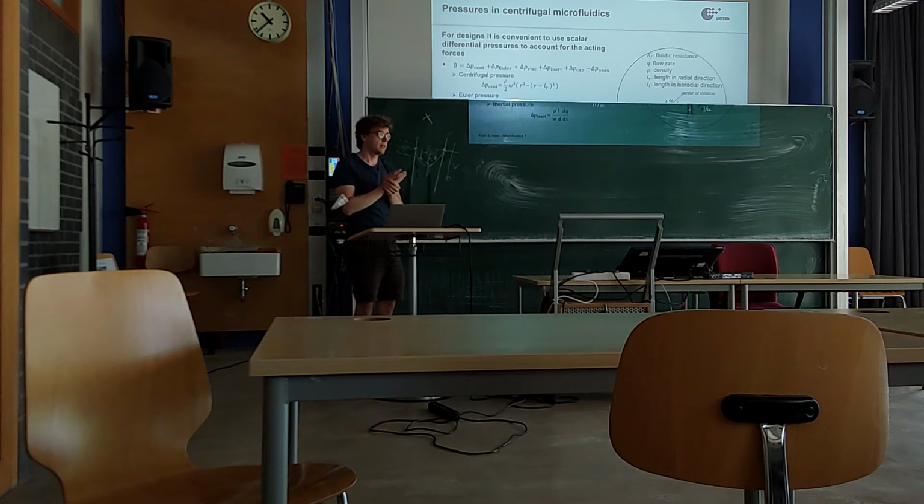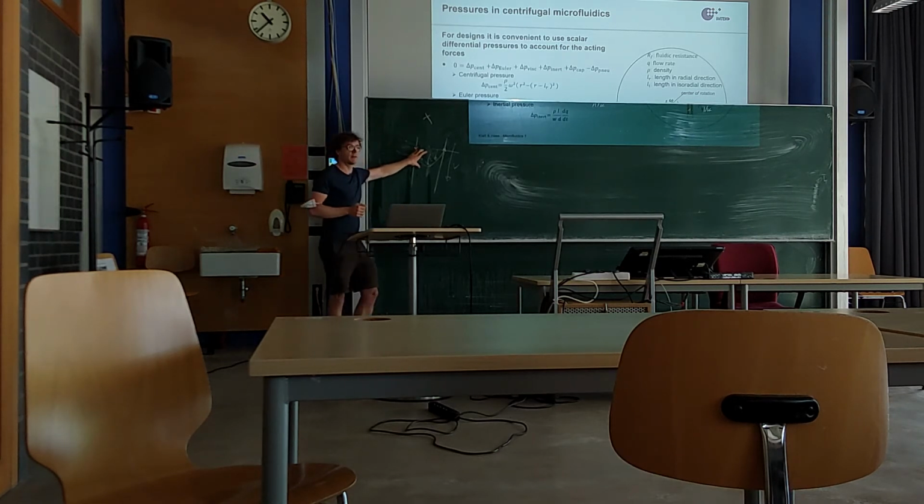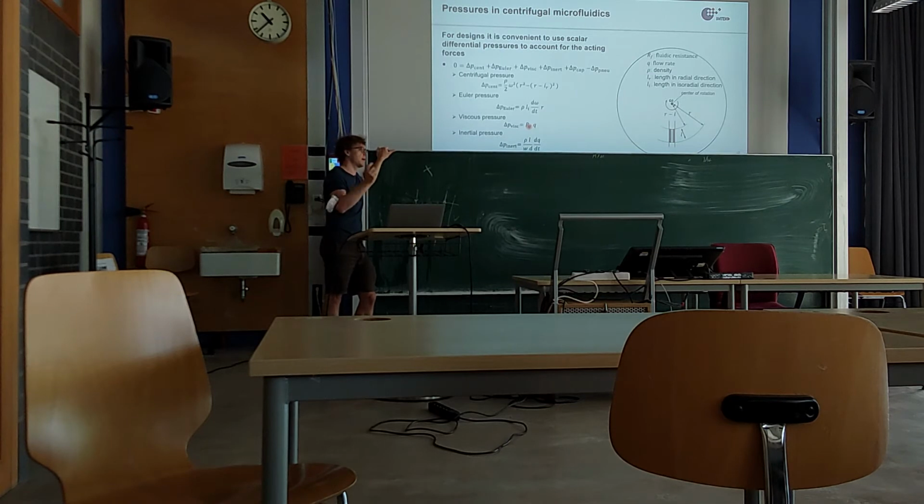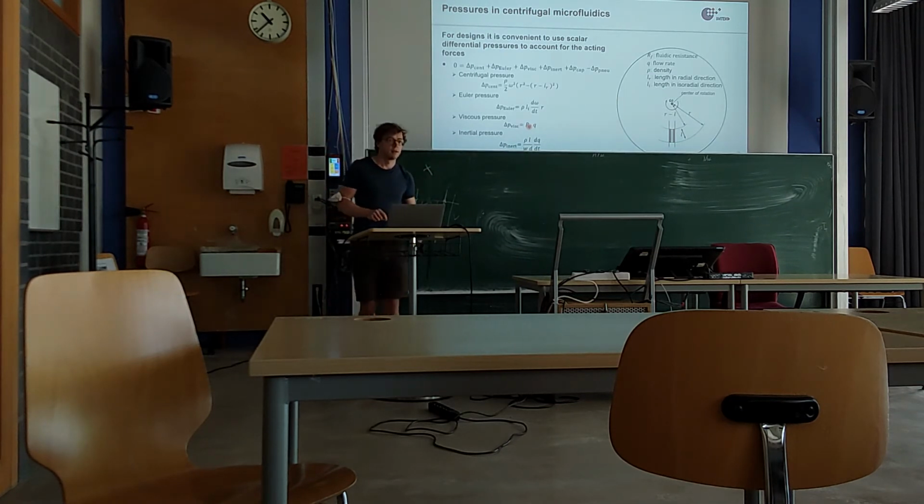That's what Niklas presented last time, and I think also in the calculation and simulation modeling lecture. And the resistance value, you will get it once again from this idea that there's a Hagen-Poiseuille flow profile within the channels. So the viscosity will play a role, the dimensions of your channel will play a role, the length of your channel will play a role. So yeah, you should be familiar with this by just looking at the last lectures.